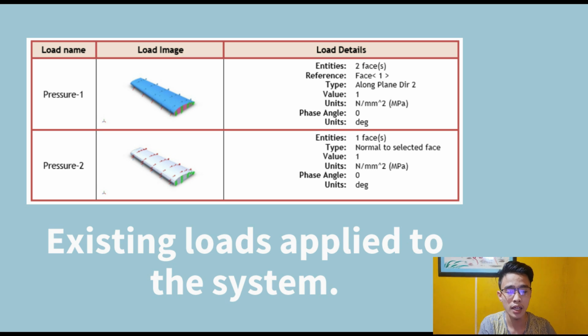Here, the lift force is named pressure 1. Why pressure 1? We consider the lift force as force 1, and while solving the force, we will consider pressure, so we named it pressure 1. Lift force is the force a fluid flowing around the surface of an object exerts on it. Lift is the component of this force that is perpendicular to the oncoming flow direction. It contrasts with the drag force, which is the component of the force parallel to the flow direction. Next, we have the sideways force, which is named pressure 2, or the drag force. The drag force is an aerodynamic force that opposes an aircraft's motion through the air.